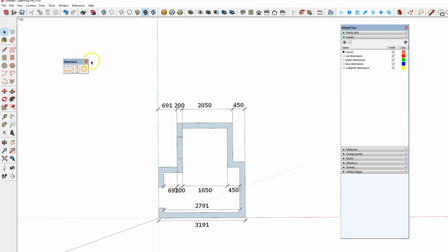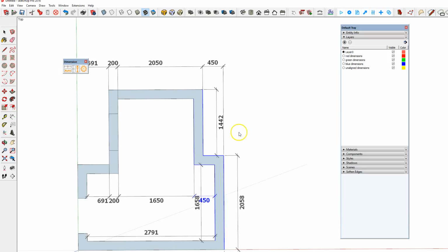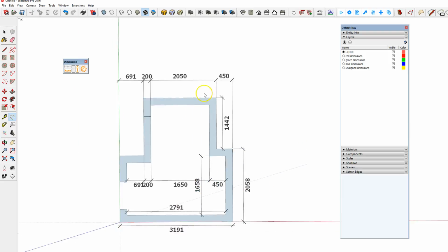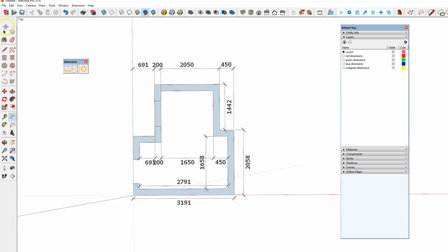And the same goes for my vertical measurements. I just need to select the lines here and hit the vertical button, and that will add those lines in. And then you can move them if you need to, a little bit like so, just to arrange them if you need to, like so, and format them whatever way you like. So let's do a gap measurement. So I'll undo those few things here.